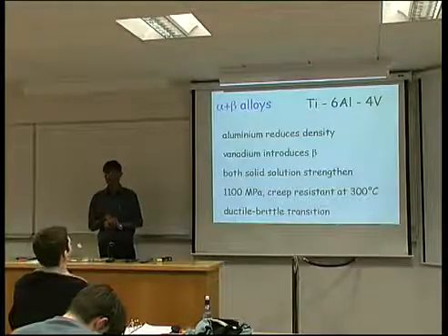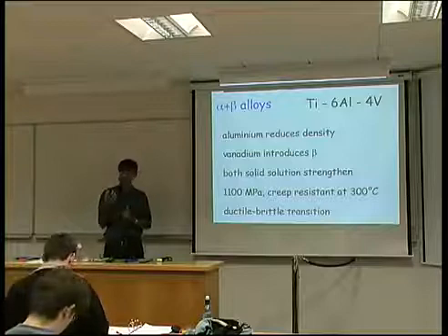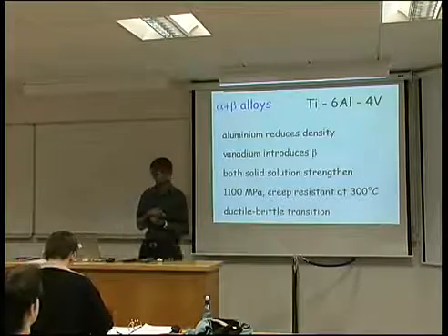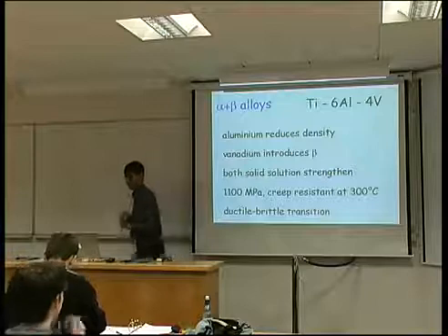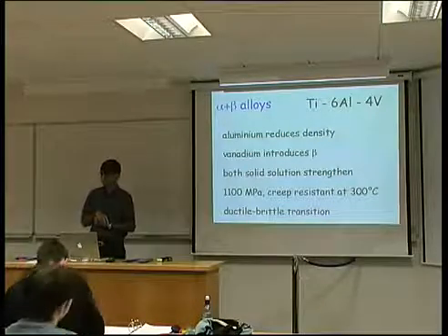This is by far the most important alloy of titanium. It accounts for the vast majority of titanium alloys marketed. It's a very simple alloy: titanium with 6 weight % of aluminium and 4 weight % of vanadium.